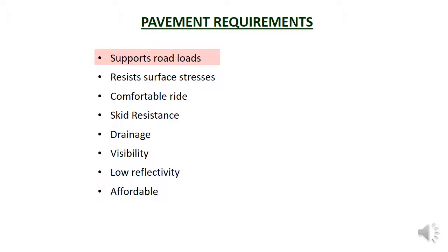One of the main requirements is that the pavement has to support the traffic loads and reduce them down to levels that can be carried by the subgrade without the subgrade deforming or failing. The pavement needs to support these traffic loads for long periods of time without breaking up. Specifically, the whole pavement needs to resist the normal stresses from the weight of the traffic and the shear stresses from vehicles accelerating, braking and turning. The surfacing and base course surface in particular are especially prone to damage from traffic loadings and need to be designed to resist the expected traffic loads.